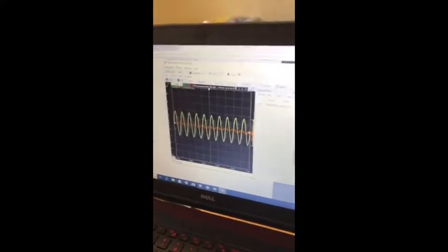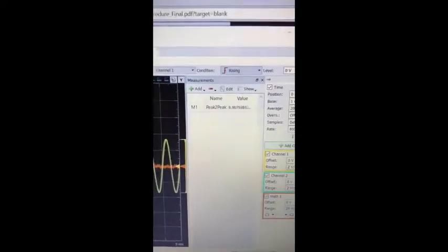We don't want that. What are we going to do about that? So we're going to change the averaging tool and change it to 20. And as we can see, it's a lot less noisy. The reason for this is because we're taking the average of the peak-to-peak voltage instead of taking it exactly at every point, which can get pretty noisy. We use this averaging tool to also get a better read of the peak-to-peak voltage, which we used using the math channel.